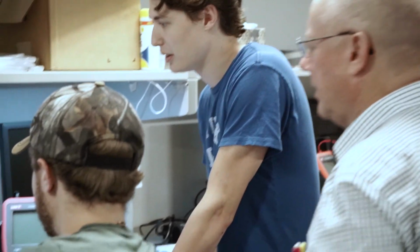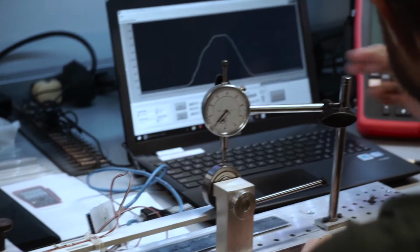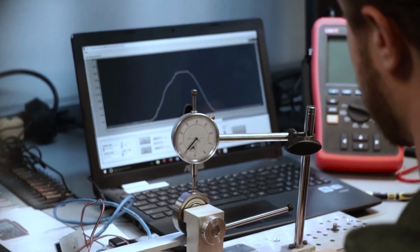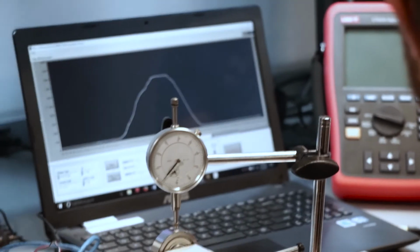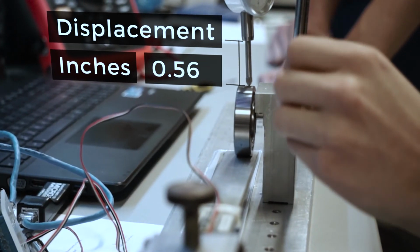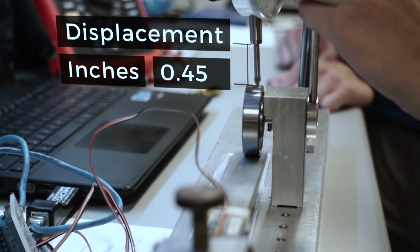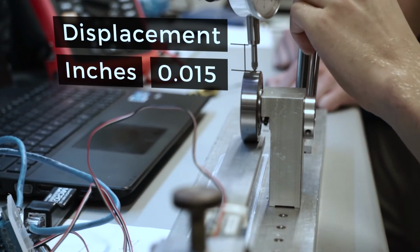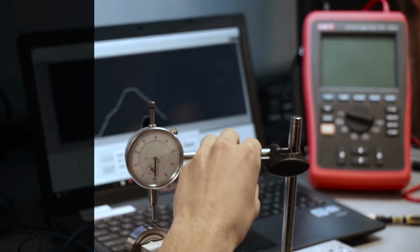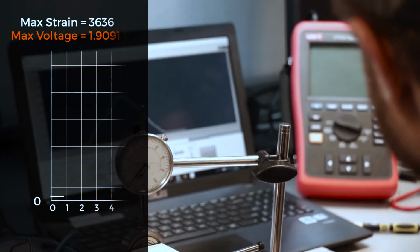Once Dr. Barnett suggested a better way to scale the y-axis of our graph, our data from the strain gauge came out very well. The Wheatstone bridge operated as intended, and as the beam was deflected from a subjected force, the strain gauge's resistance changed directly with the strain in the beam. We measured a 0.592-inch maximum deflection on the dial indicator provided. This coincided with 3,636 microstrain, which directly correlated with the voltage change of 1.9091 volts.